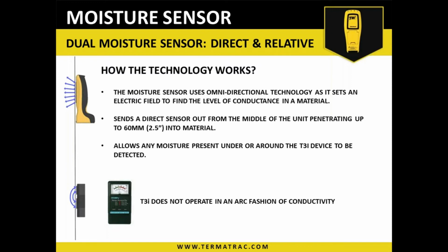The Termite, however, operates a little bit differently. It operates on a capacitance-based conductance, so it is continually discharging and re-energizing. So it takes its readings a little bit different. It goes on speed of between full discharge to re-energization, including certain levels of impedance, which will then make the needle move to give us an indicative reading of moisture.